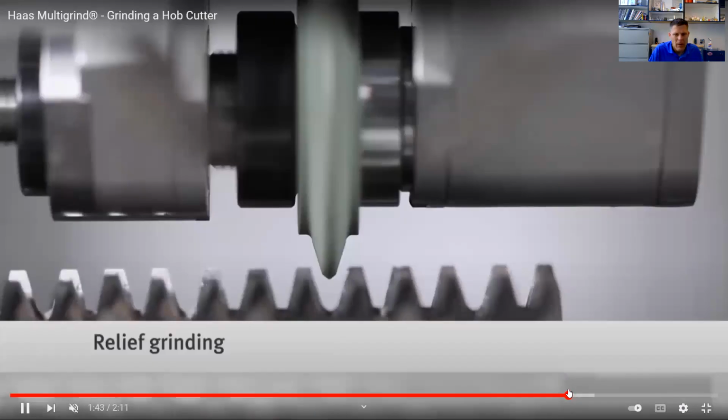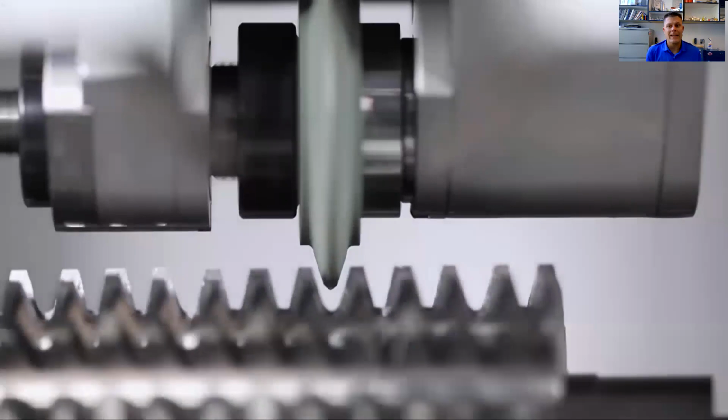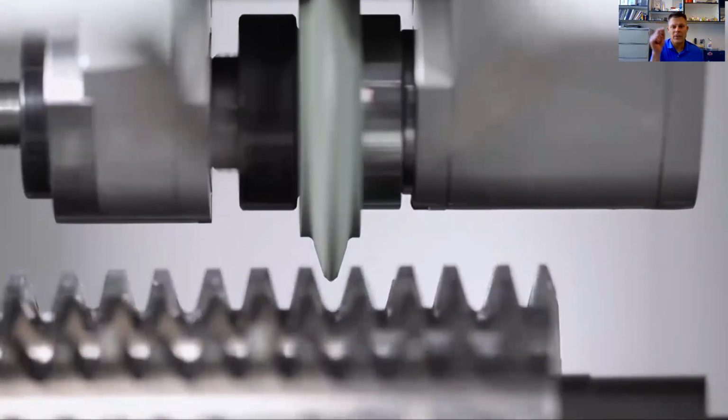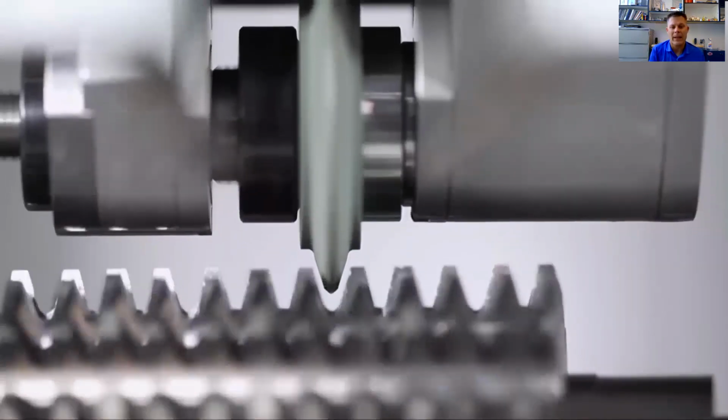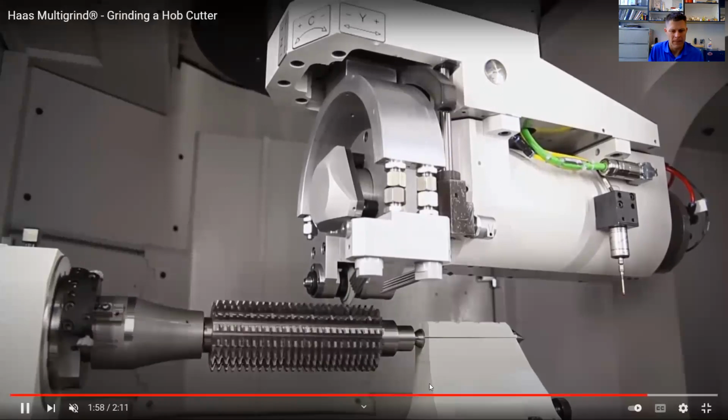So I'm going to come over here, actually, is what I want to show you. I think it's right here. In CNC grinding, you have a form tool. The CNC machine uses an industrial diamond to shape the grinding wheel in the exact form that you need. Hence the involute curve for the gear tooth right there is what they shaped it in.